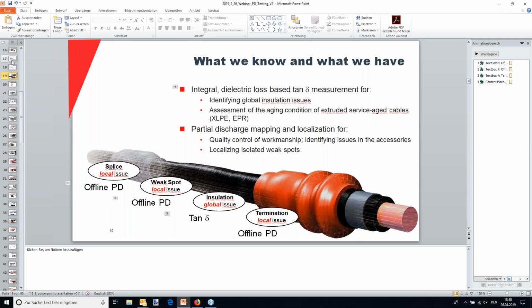We have this from at least 3-4 very different utilities, and they're all similar and they're all dissimilar to a certain extent. In the standard itself, in IEEE, there is not an absolute value established, but we know from experience that a few hundred picocoulomb is typically what you see, and then it goes up into the thousands.